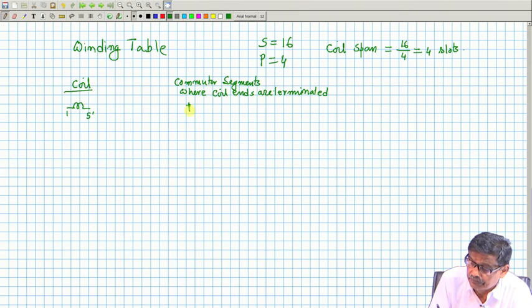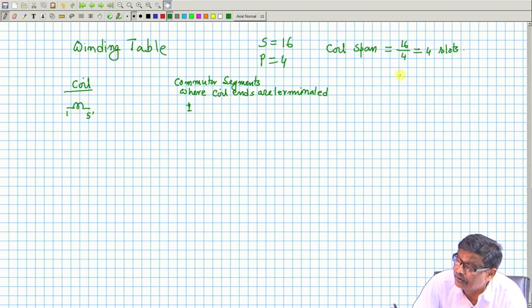It will be in 1, that is 1, I will terminate it, this is the coil. I will terminate it in commutator segment 1, and next one, its return, I will terminate it in commutator segment 2.